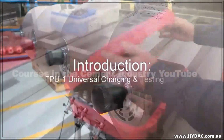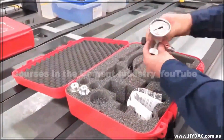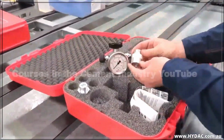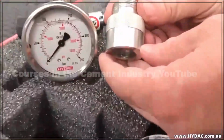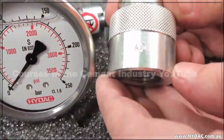The HYDAC FPU1 Universal Charging and Testing Unit can be fitted directly to HYDAC diaphragm and piston accumulators, but it uses an adapter to connect to a bladder type accumulator. This is known as the A3 adapter. It is clearly stamped A3.